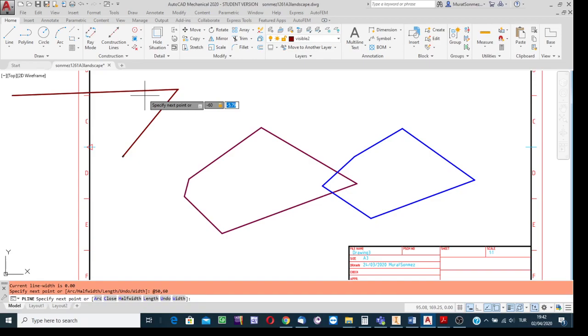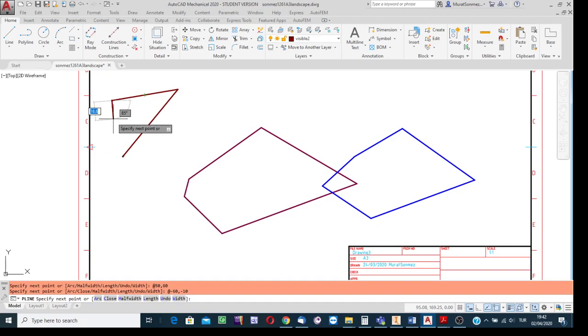Say that the line is to be created in the down direction, so write the delta y value into the third box as negative. Say that its value is minus 10, and then press enter. Yes, here it is. That is the line. I think it is clear enough. Two different cases studied. Creating those lines in the scenario where I said that we know length and angle, and creating these lines in the scenario where we know delta x, delta y values. I hope these are clear enough.